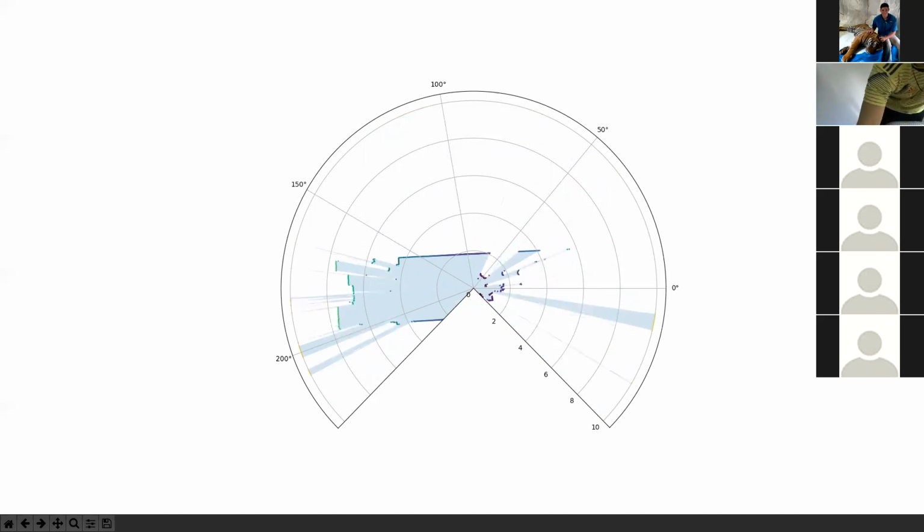Back to the walls. Before that, Daniel, we know that zero degrees, looking straight ahead, would be in front of the LiDAR, right? So it's basically what's in front of it. It will be the 0 in this plot, right? Yeah, at least in the L1 LiDAR. In this plot, it's not correct. 0 degrees is on the right side, 90 degrees off. But on the L1 LiDAR, 0 degrees would be directly in front of you, and then it goes from minus 135 degrees to positive 135 degrees.